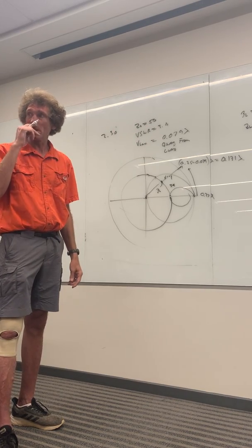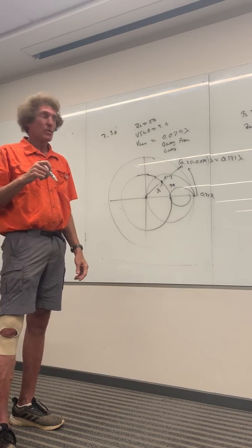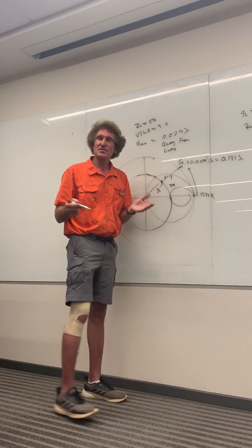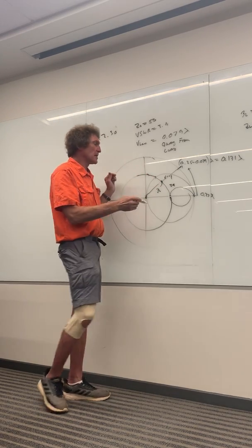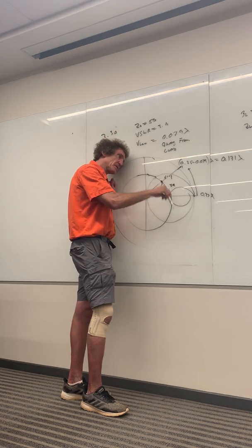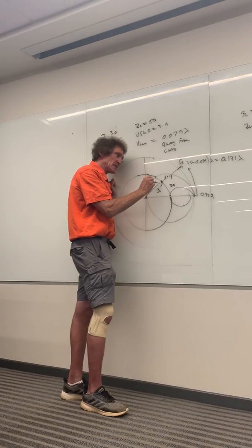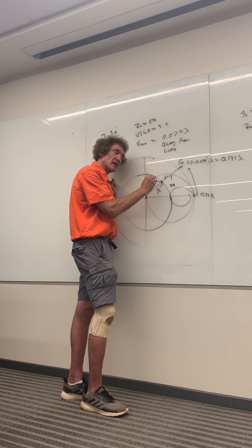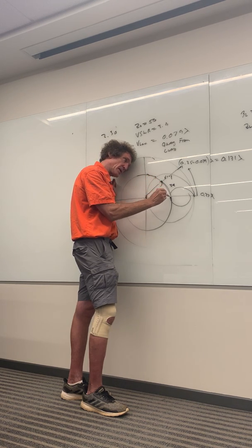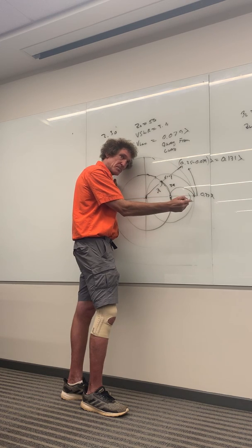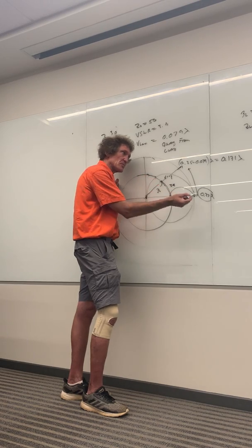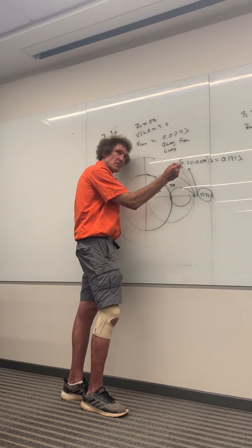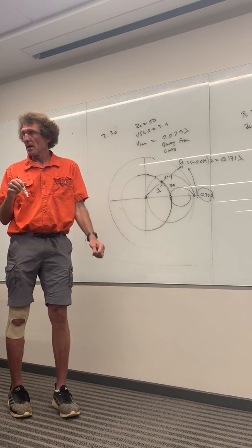Everybody follow me there? How did we know how to subtract or not? You could use the other scale, but I'm using the outer scale because that's the one we always use. If you come in here, you're at the load. When you move this way, it's wavelengths towards generator, right? They said the maximum was 0.079 from the load. So what we need is this arc distance to be 0.079 lambda. This is 0.25 lambda, that's the mile marker, so we subtract 0.079 lambda from it, and we come here. That's 0.171 lambda. All right. Does everybody understand that?